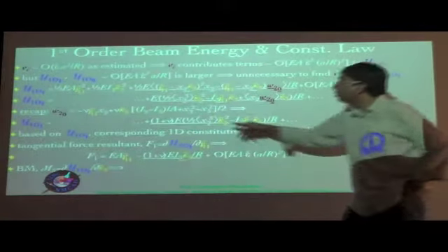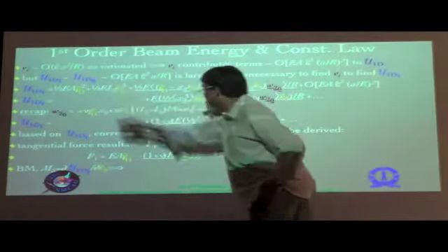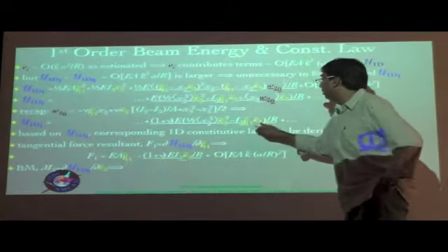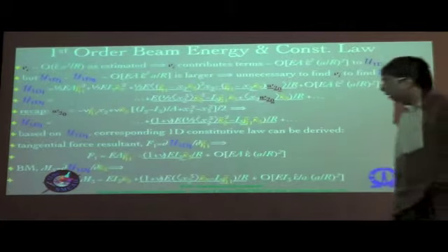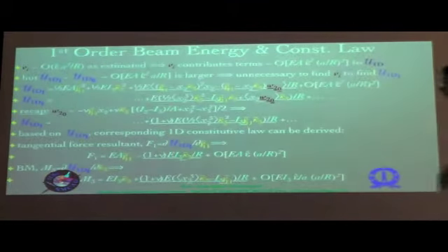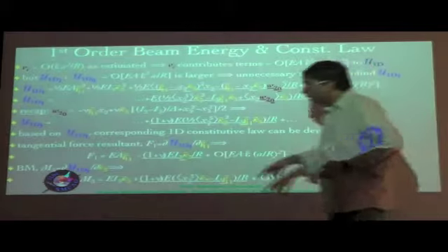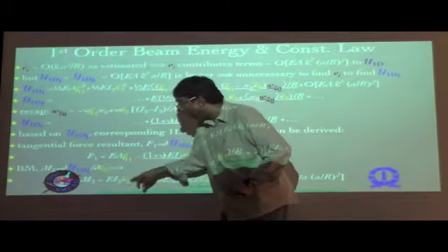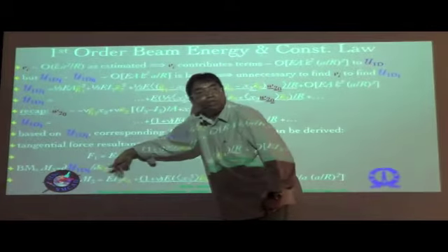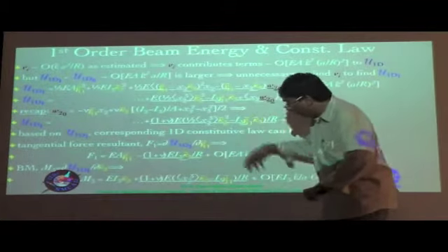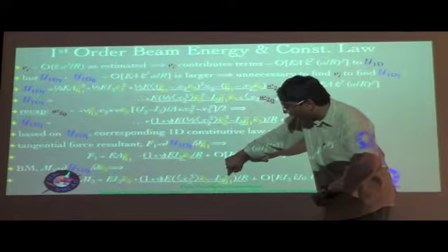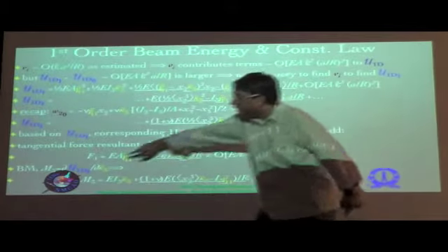So all that you have to do is to take the derivative. This term would contribute. Similarly, this term and this term would contribute as well when you take the derivative with respect to kappa 3 bar. And this is basically what it boils down to. So again, this is what we already had. Bending stiffness times the curvature is the bending moment. Again, very familiar. In addition, of course, this term, the axial strain contributing to the bending moment.